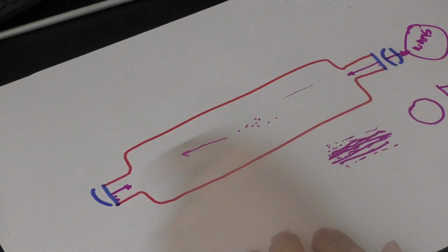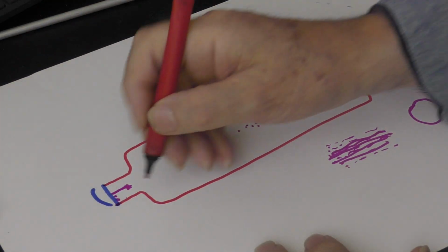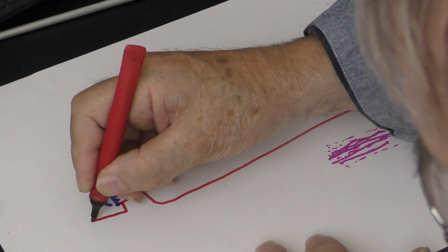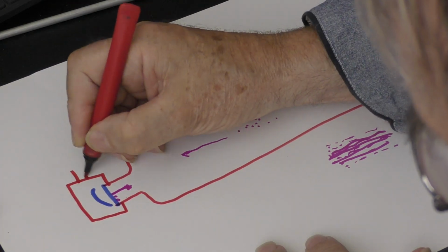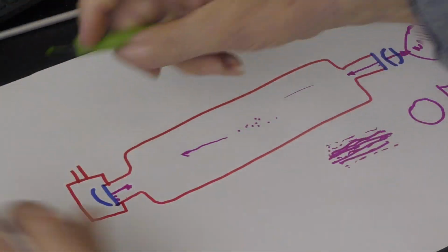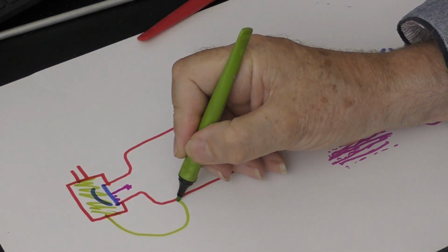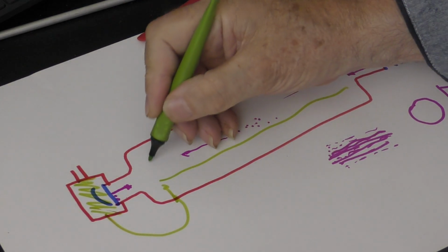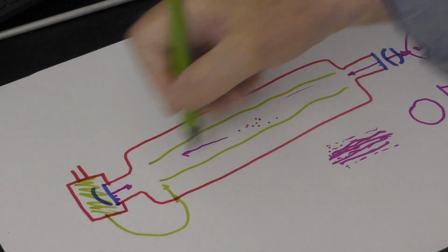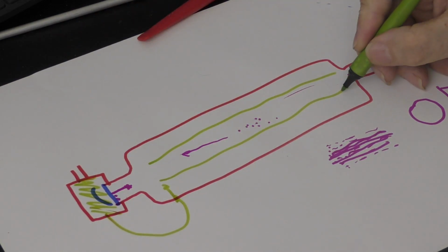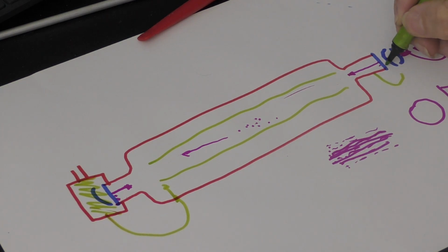Now, these mirrors get hot, and the way that the laser manufacturers deal with that problem is they encase the mirrors and they put water through them that then eventually goes back into your tube and runs around the outside of your tube to cool the main ionization tube. And then it comes out of here and it passes through another cooling chamber here and here.